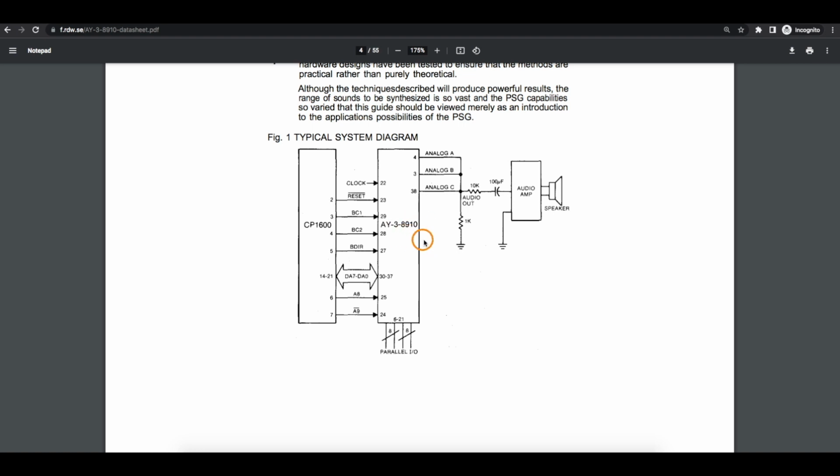I thought the chip was broke, but after trial and error, as soon as I reset this chip pin, the noise channel started working. So I made sure I connected this to the Nano so I can always reset this when I'm initializing after power up.